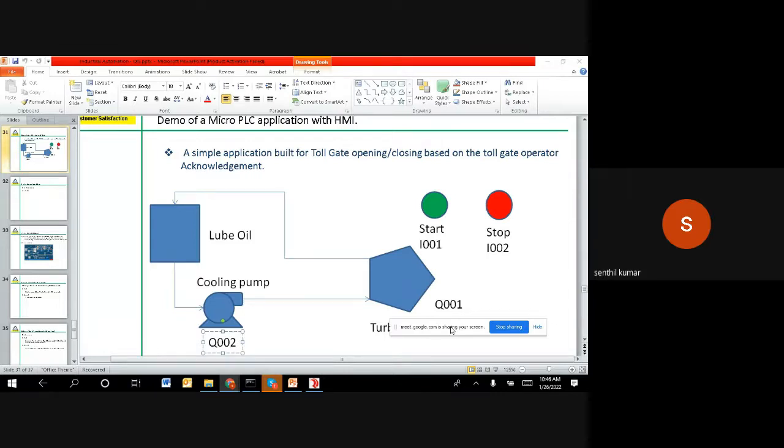When it goes on the way, there will be a sensor. It will sense one bag, two bag, three bag, four bag, and if 100 bags are to be produced for loading one lorry, then after producing 100, that specific conveyor will stop, and the other conveyor will start for another lorry. So this will shift the belt to a different route, so that it continuously discharges the predefined quantity, using the sensor and a counter in the PLC block. That's the application.